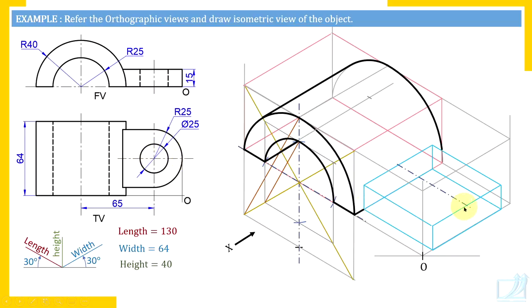From the right end, the extreme right end of the surface, measure 25 millimeters parallel to length. Then draw this center line parallel to width this way. To draw the center line, first measure 25 millimeters here and set the roller with 30 degrees line, roll it to draw this line. So we get those center lines.